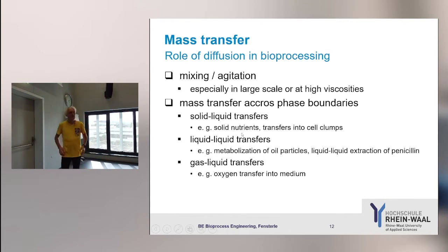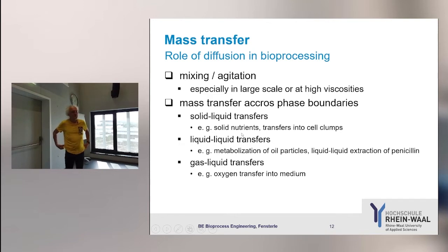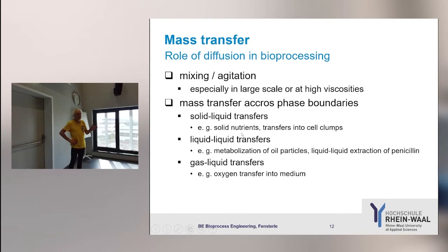So when you have a membrane, is diffusion greater than convection? Like, is it a stronger motivator for utilization? At the phase border, it's of course a transport via the phase border. There, usually it's not convection. There you don't push it through. So at the very beginning, what we said, this is just the phase border difference. There, it's just the difference of concentration and just the area. This is the same as Fick's law, just with a step change. So it's a delta and not a d.